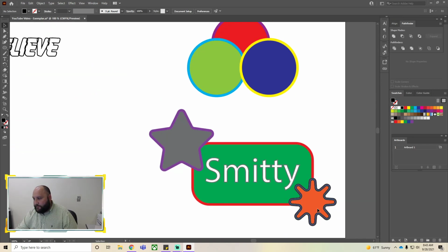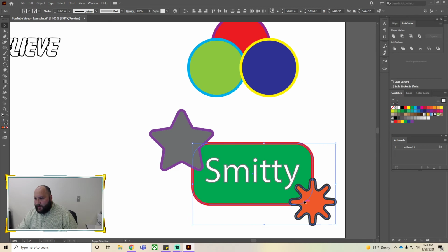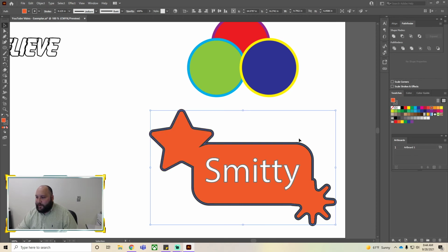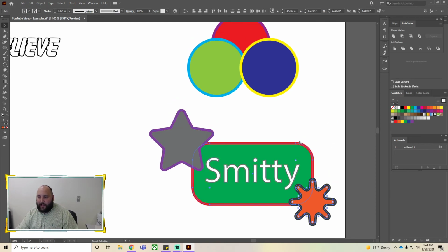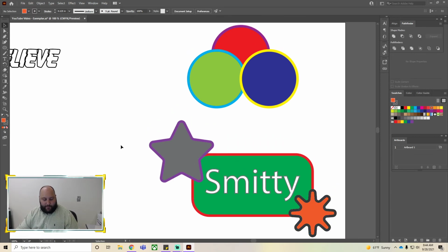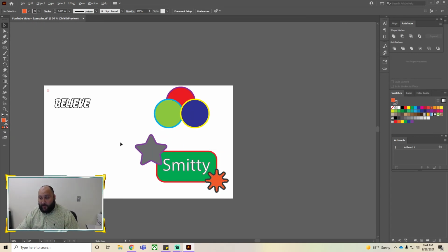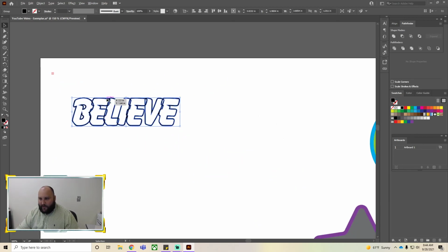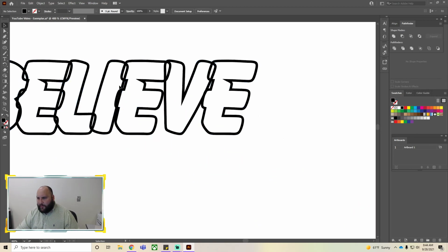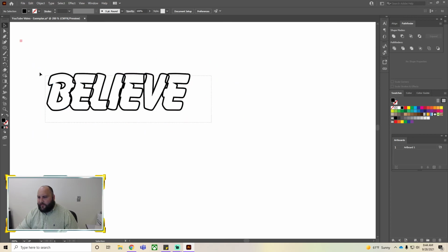So let's say maybe I just highlight these two and then hit it. See how it united those and kept the properties of the one on top. Then maybe I highlight those two and it united those and kept the properties on top. But I kind of like the way my logo looks like that. So that's just a little bit about Pathfinder, the shapes. I'll give you a good example of text later. I think maybe because there's so many overlaps, this didn't work.